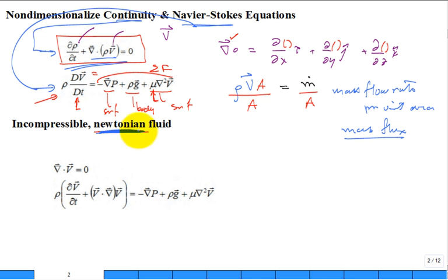What does the Newtonian fluid mean? Well, the shear stress is proportional to the shear strain. You can write it in 1D, like partial of u with respect to y. That's a simple way of writing it, but it's proportional through this constant of proportionality known as the viscosity.